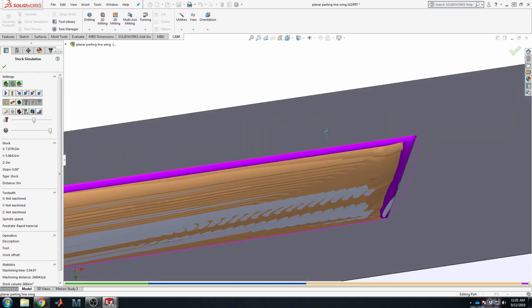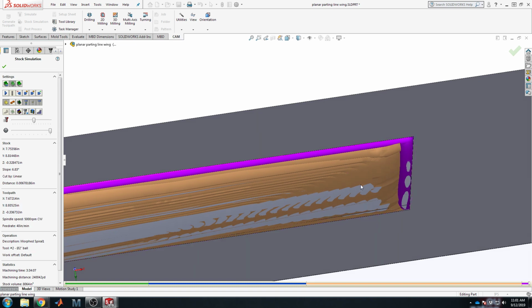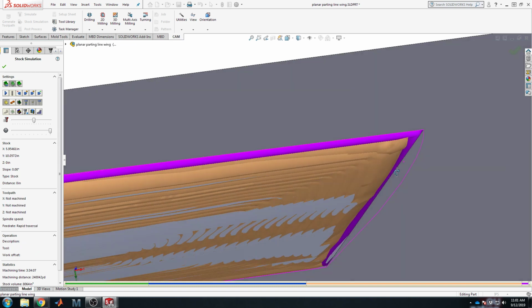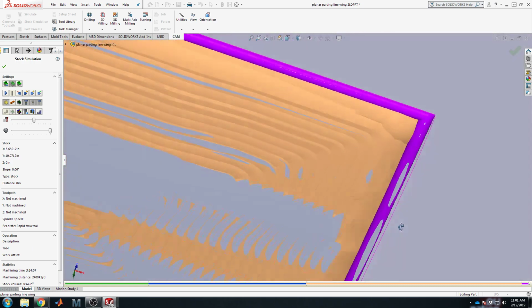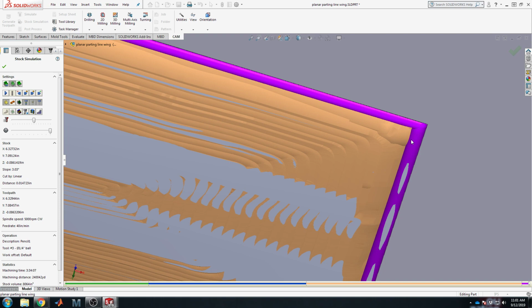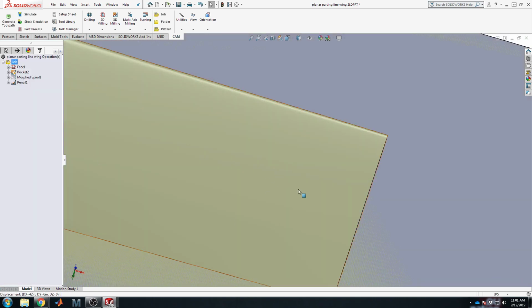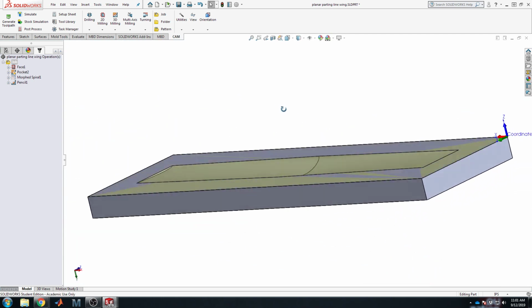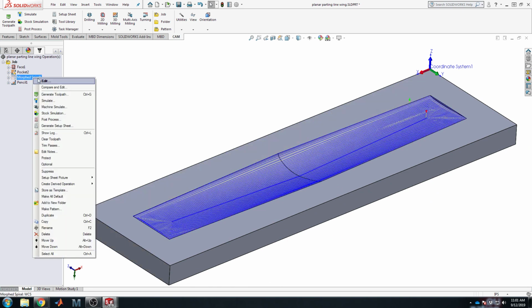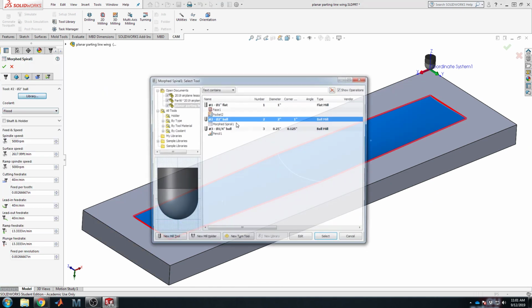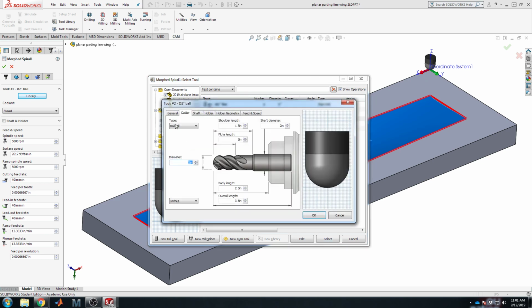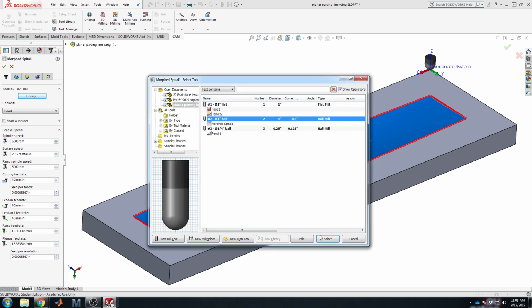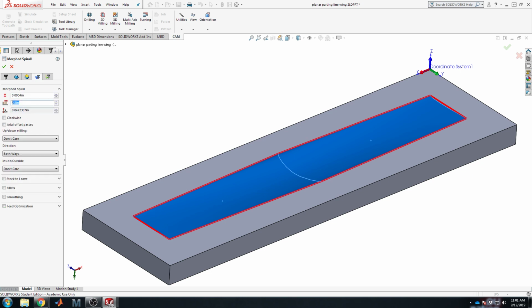And yeah, that still leaves a lot to be desired for me. It helps on the edge, but you see it's got that really odd and poor material that's left right there. So there's nothing saying you have to get into that corner perfectly. Keep in mind that rounding off corners is just fine. It just means the part you make from that mold will have rounded off corners. Really, in this balance, I would probably go back to something on the order of a 1-inch ball diameter bit. Select that there. Step over. Yeah, we'll call that about good.